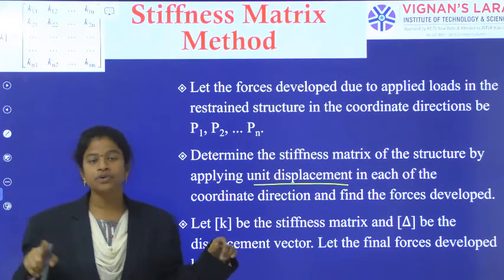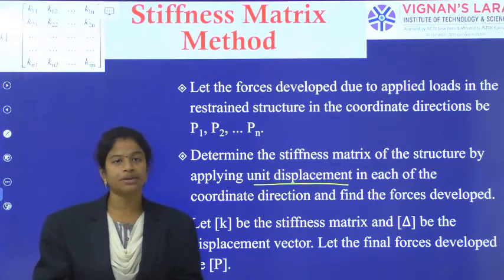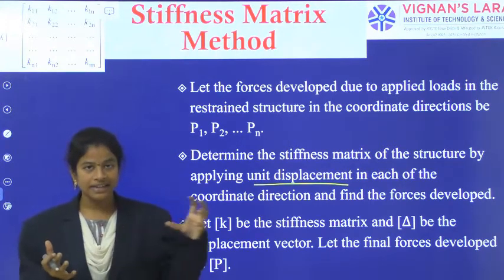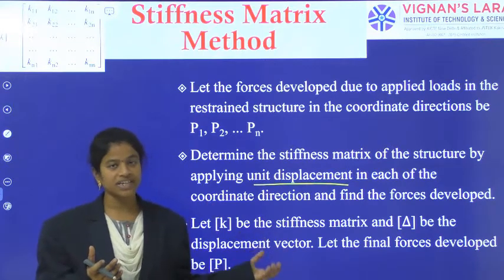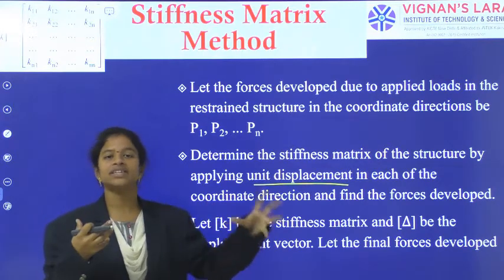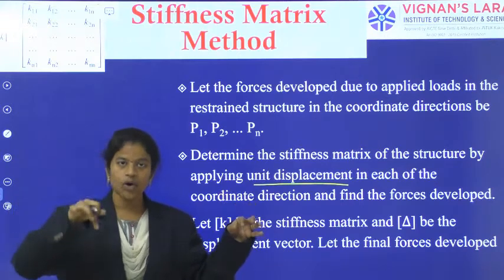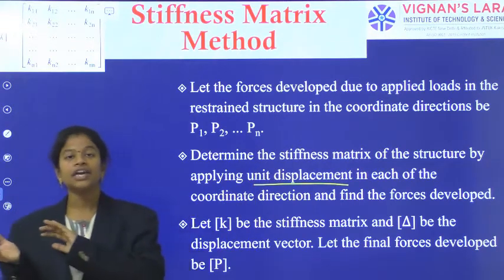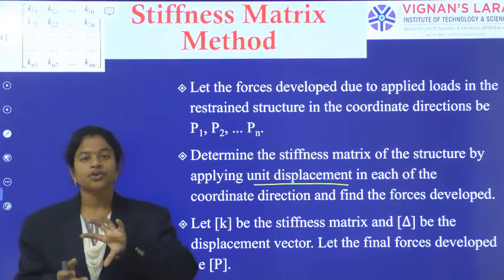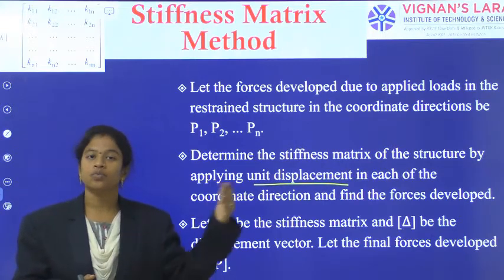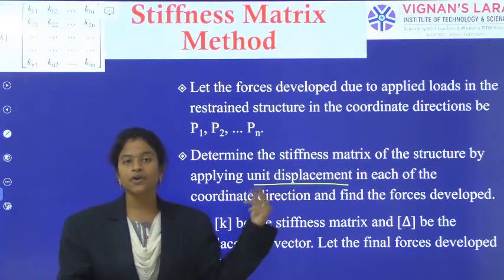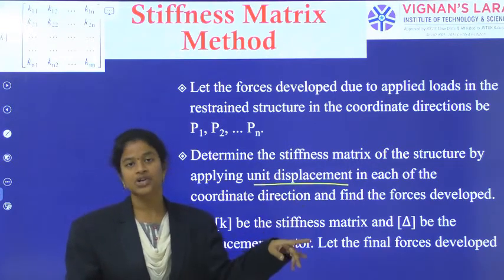Using the conjugate beam method, we calculated the displacement from the force: if the force is a moment, what is the rotation generated, and if the force is a load, what is the displacement generated. Here I am applying a unit displacement. Due to the application of unit displacement or unit rotation, what is the force or moment developed? That we have to calculate.